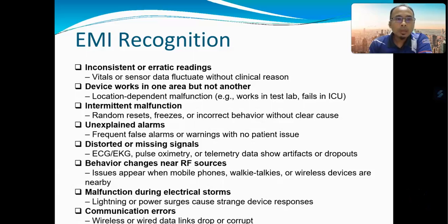Okay, now how to recognize EMI? There are a few signs that can be used to identify or recognize EMI. This slide shows a few types of recognition. The first one is inconsistent or erratic readings. For example, vital or sensor data fluctuate without any clinical reason.